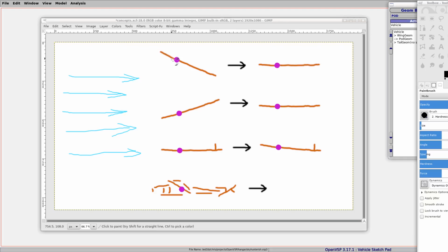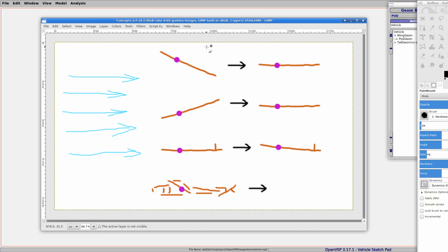So if the angle of attack is high, it's going to see an anti-clockwise moment, or a torque, or some sort of twisting force as the result of that. If the angle of attack is negative, it's going to see a clockwise twisting force, so it's going to end up like that. This is pretty simple for these two cases, it's obvious. But the point is that the angle of attack relative to the wind is going to determine which way this twisting force goes. And this also has a name which we're going to be looking at in the program, and this is going by the name of coefficient of moment, I think it is.